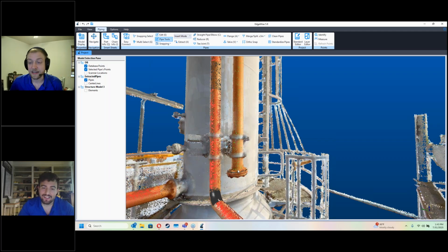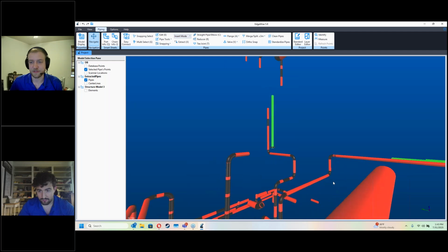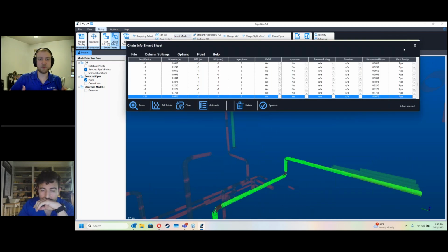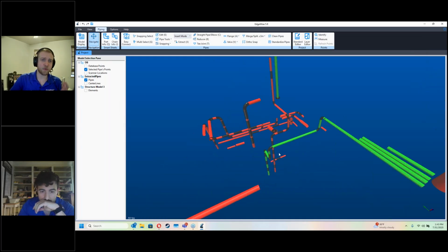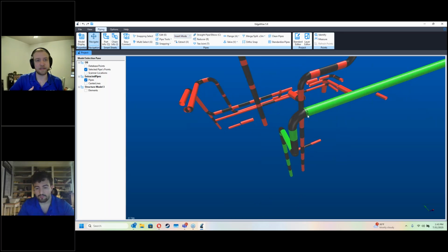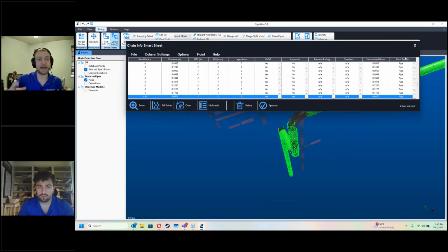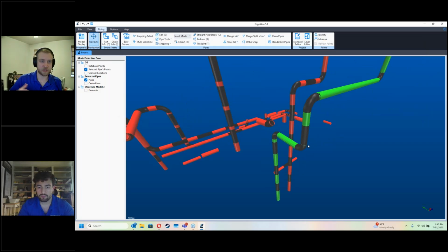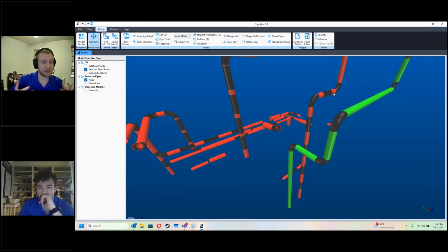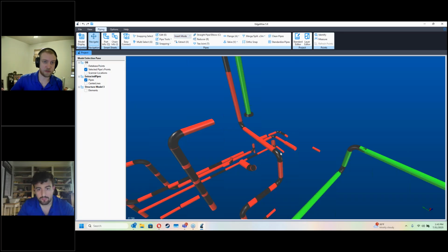Let's see. You do need to apply standards before you can apply valves and flanges. So that is a core part of the workflow. So the general overview here, now that we have the clipping box and the workflow improvements, the idea is that what we're recommending, instead of just saying, okay, here's this giant model with all the stuff that's generated, just start going through it, is to section out zones, just like you would for any other project.